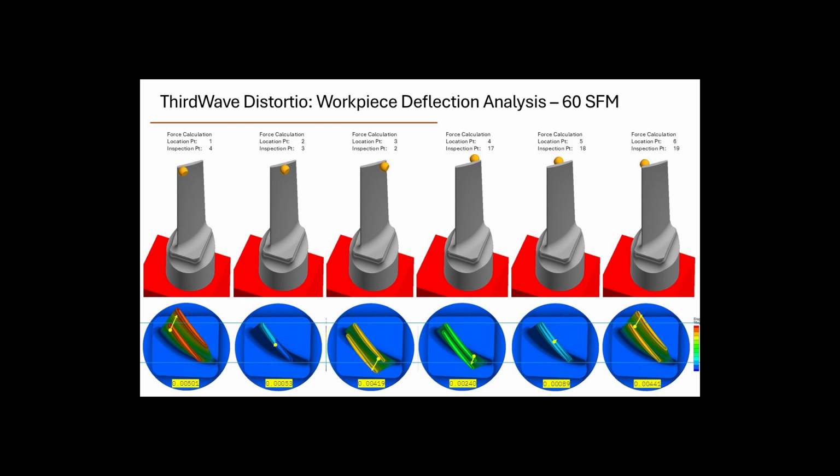So what we do here is the tool path, the tool, the actual workpiece, the materials, everything is defined in NX, right? Because we're starting off with model-based definition. And Third Wave has a plugin to Siemens. It's a button click to export all that data out into Production Module, so I don't have to do any setup.